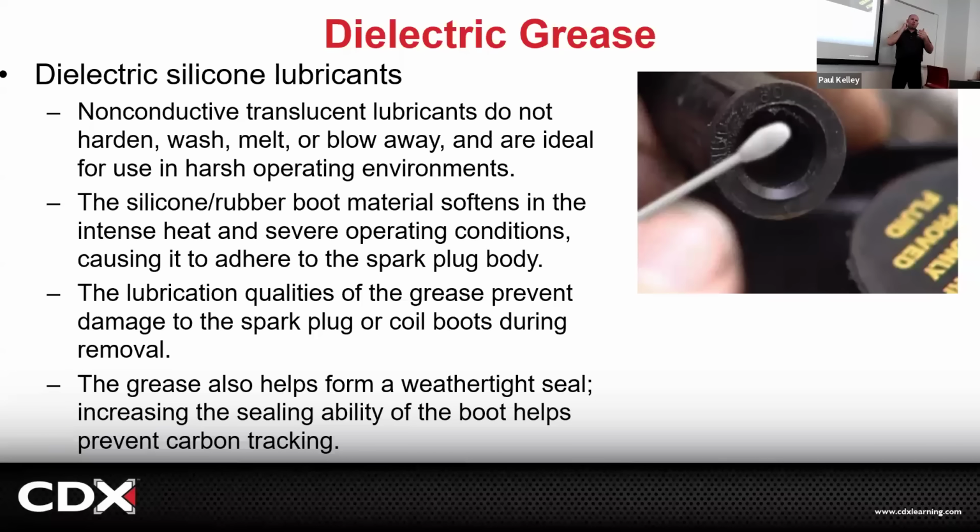So it's nice. Exactly. So if you're going to be a good, detailed mechanic, put a little dielectric grease in there. They'll slide on easy. They'll slide off easy. Whoever works on it next will be like, whoever worked on this before, I like them. If it's you, you're going to like yourself. If you don't use the dielectric grease, you're going to hate yourself, and it causes a lot of issues. And there's treatments available for that. But that's not what I do. All right. So this is just a good way to do stuff.